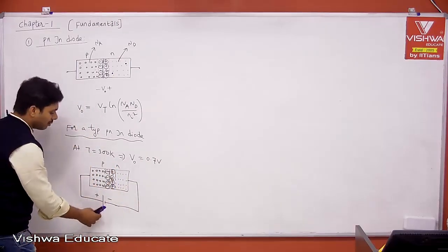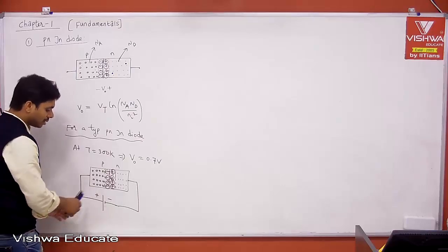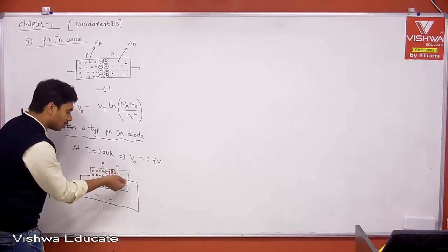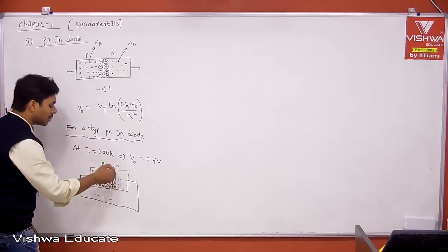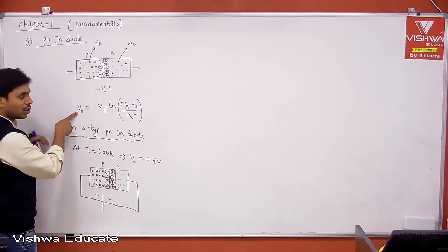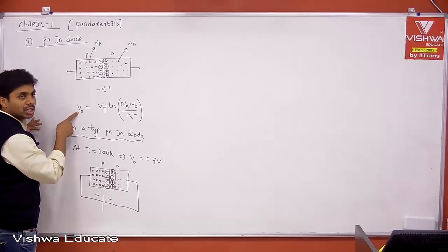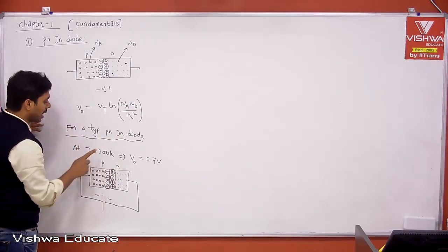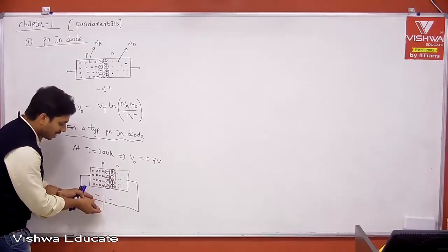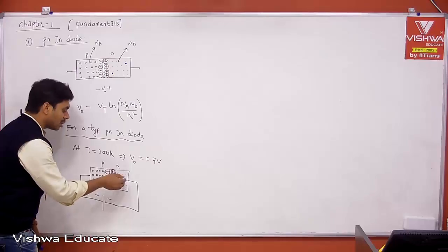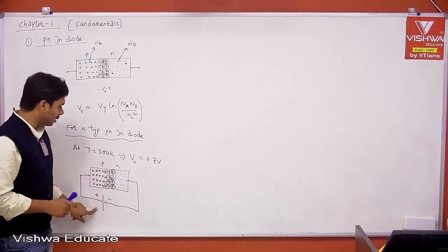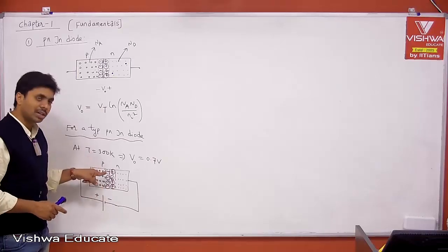When you connect forward bias, the battery is what gives energy to the carriers in the n-type to cross the barrier, overcoming the depletion region. The depletion region voltage, which we already derived, is V naught, the contact potential. For a typical doping concentration at room temperature, V naught is 0.7, so I need to apply that much externally so the electrons will overcome the barrier. Therefore, this is the minimum voltage we need to apply so the battery can overcome the barrier inside the p-n junction diode.